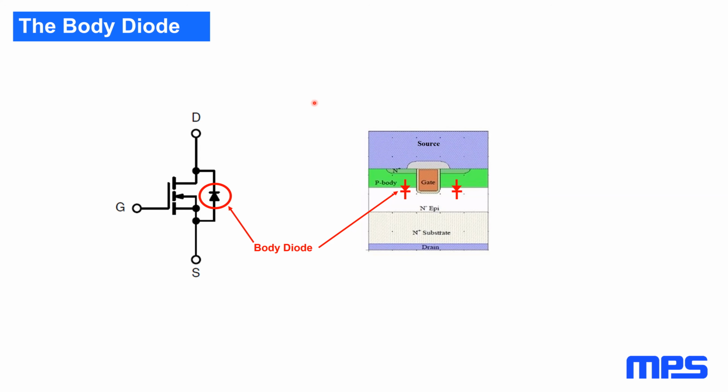When the low side turns off, the high side body diode takes over and takes the current back to the supply. You just have to be aware that it's not a great diode. It's not a Schottky diode, it's a silicon diode. But generally, most MOSFETs are capable of taking as much current through the body diode as they are through the channel.